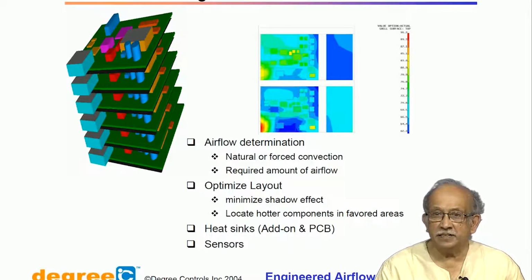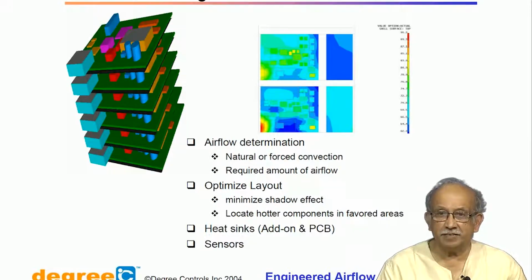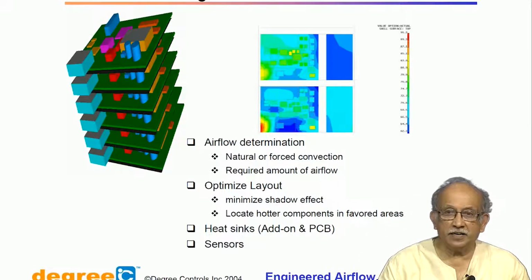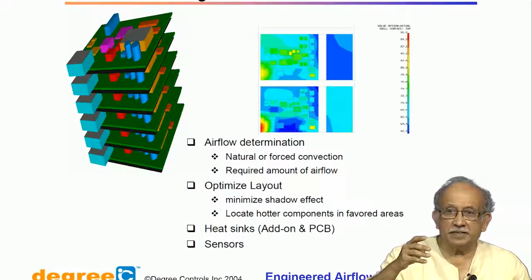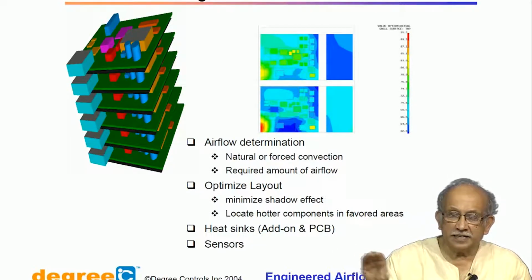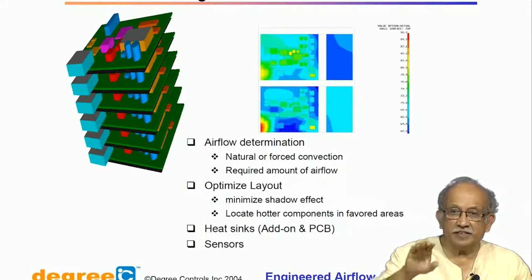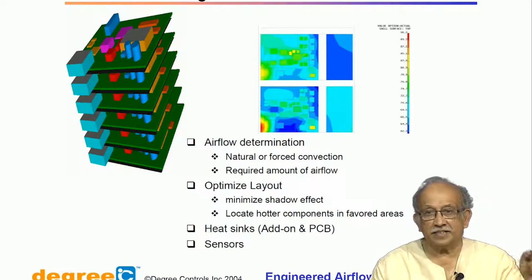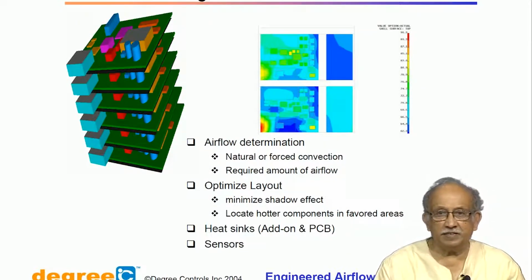Then how do we deal with it? That is where your design thinking comes in, saying try various alternatives. I have given you an example earlier saying we had a rack of, I think, a total of 6 sub racks, and the only thing we could do is allow inlet air after the third sub rack and then exhaust the air that is already pre-warmed, and it works like that.